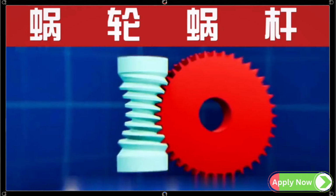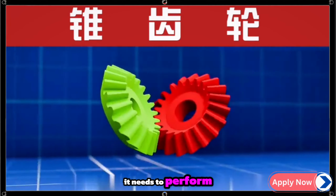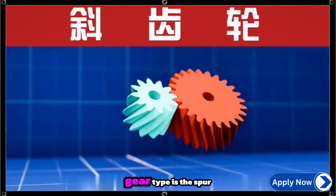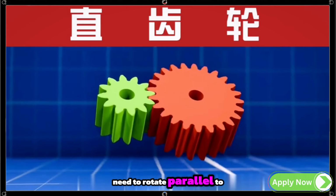Not all gears look or function the same way. Which type of gear is used depends on the specific task it needs to perform, such as shaft orientation or required force magnitude. The most common and basic gear type is the spur gear. These gears have straight teeth. They're used when two shafts need to rotate parallel to each other.